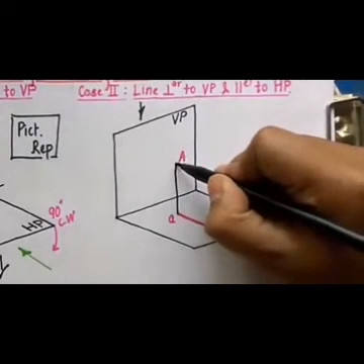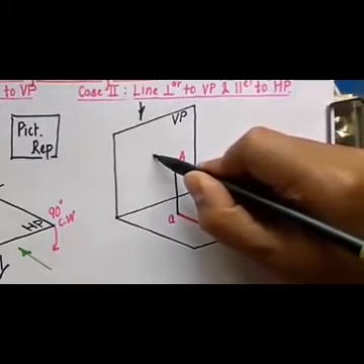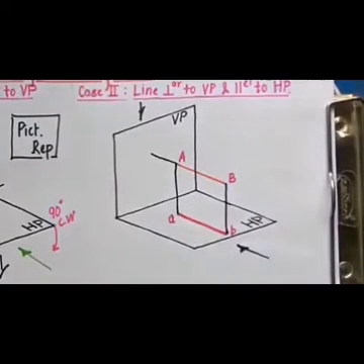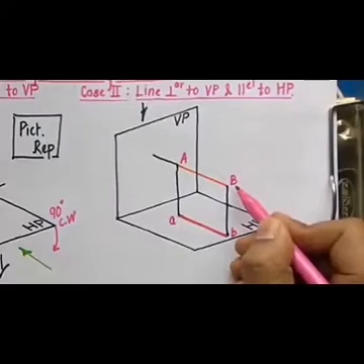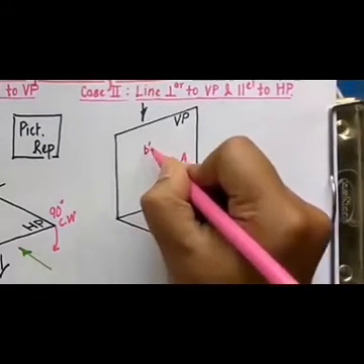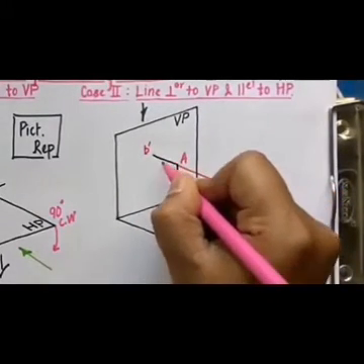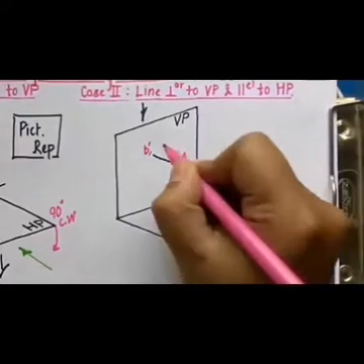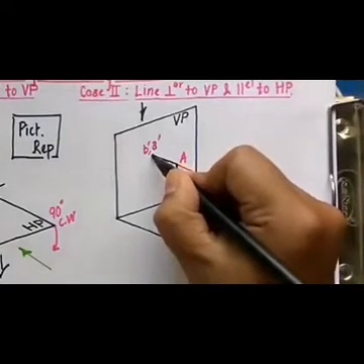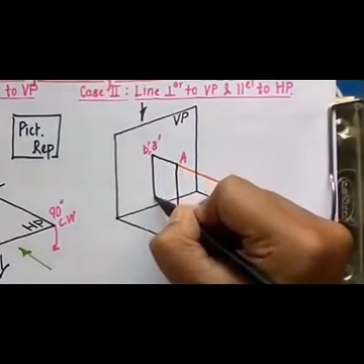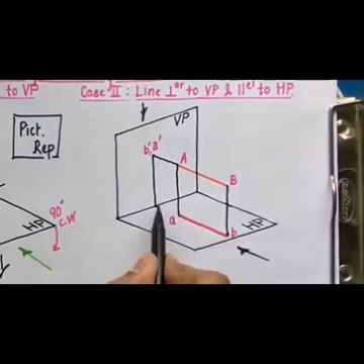Please watch this carefully. This is where you're going to have its front view. When you look at this line from the front, you'll observe this point that is going to be B dash, and behind B dash, overlapping in the form of a point, is point A, that is going to be A dash. The next thing to do is to join these so-called front view and top view with the help of a line, and we are doing so with this.